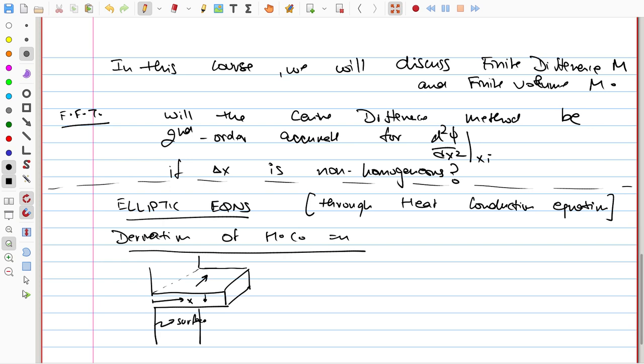So, along the depth it is symmetric, that is the reason you are not seeing that. Along the thickness it is so small, because it is such a thin fin, that you will not see much of a difference between the top surface and bottom surface. So, this is an assumption that we take, although it might be finite in terms of temperature differences along different directions, but let us assume that in this situation the temperature only varies as a function of x.